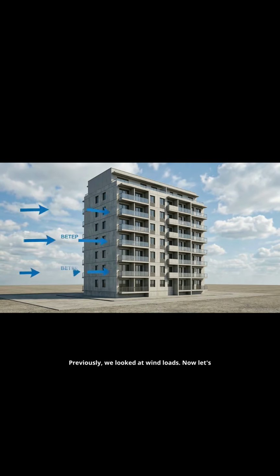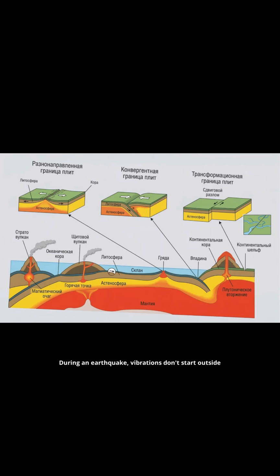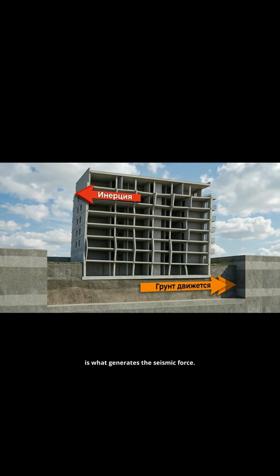Previously, we looked at wind loads. Now let's examine seismic impact. Seismicity is also a horizontal load, but its nature is fundamentally different. During an earthquake, vibrations don't start outside the building, but right beneath it in the ground. The building's foundation starts moving horizontally with the ground, but the building's mass tends to stay put due to inertia. This discrepancy is what generates the seismic force.